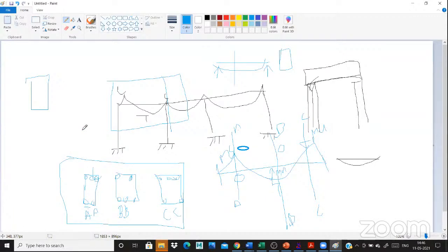If you go for a continuous beam fixed in a residential building, it is compulsory to take two cross sections for the single beam. Why? The beam will be taken into the compression zone, where the beam moment becomes high, and the tension zone, where the moment will become different. So you take the moment and design the reinforcement details. That is the basic condition for designing the beam and taking the reinforcement detail.